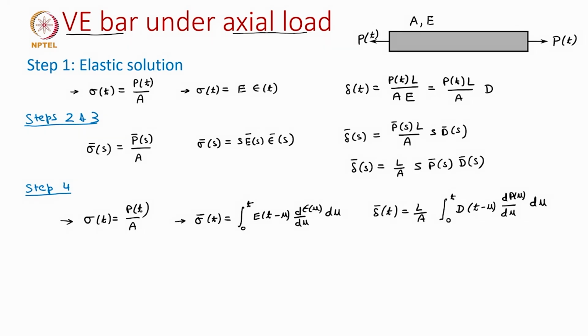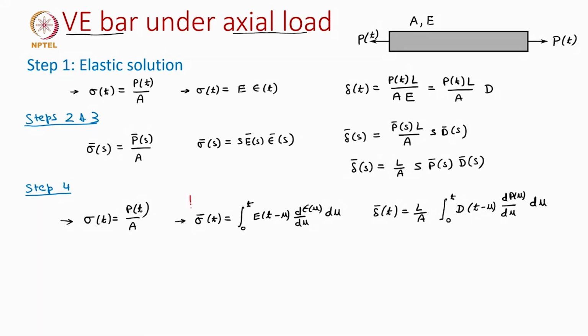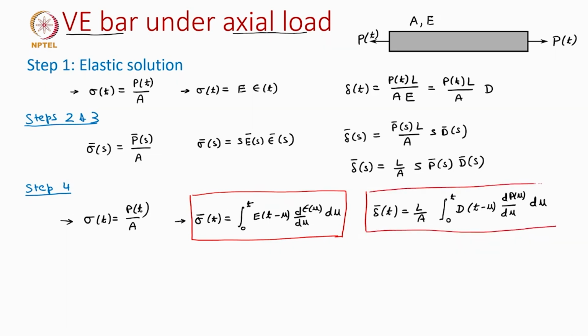So, essentially now we are able to show you the solution for the stresses in the viscoelastic problem, and we also show the viscoelastic solution to the deformation in the axially loaded bar. But mind you, though we have a solution in the time domain, we also have a solution in the Laplace domain.